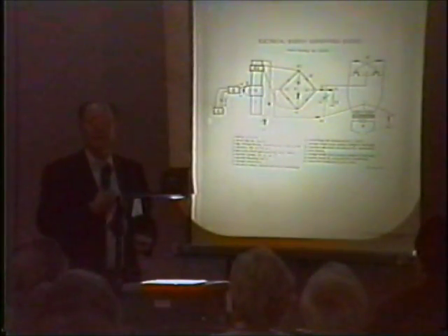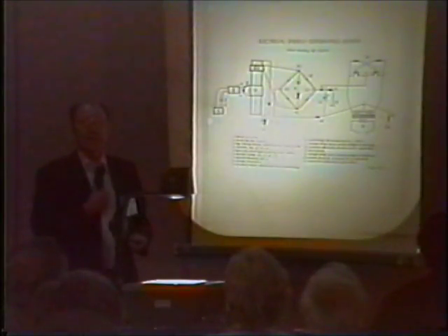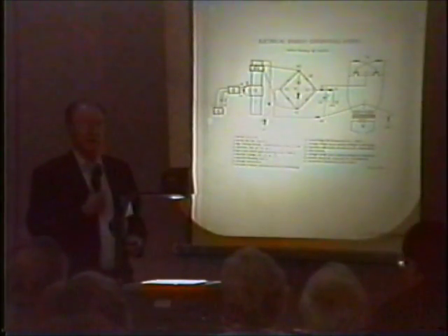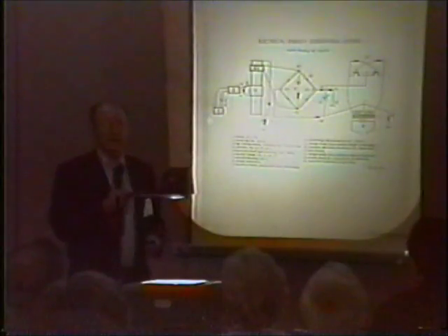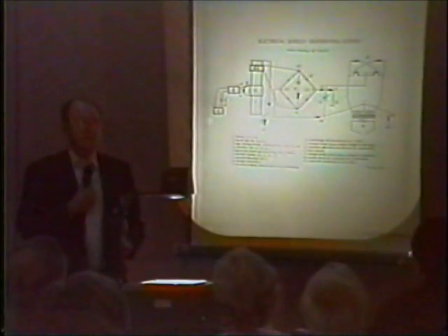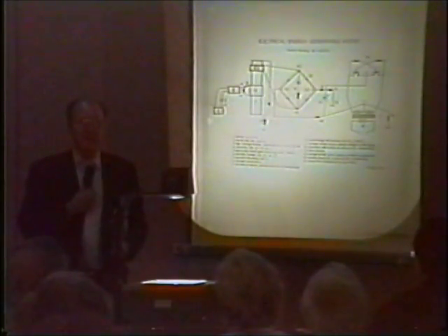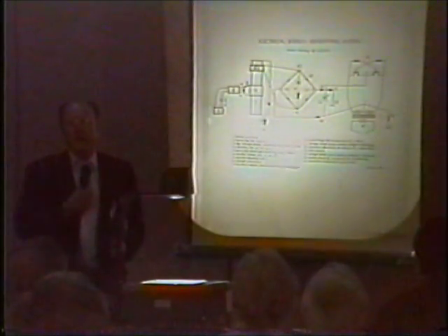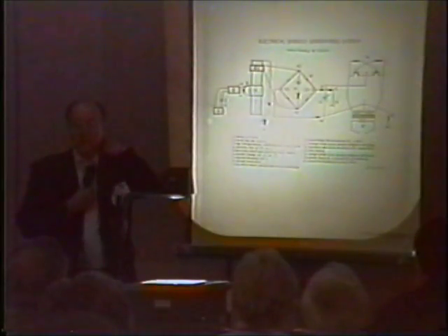What size of resistors do you use for a voltage divider here? Okay, you'll have to determine those experimentally, and again, as we were talking earlier with some of the people, resistors are not necessarily resistors. If you use your LCR meter, you'll find that almost 100% of your resistors have capacitance and inductance.